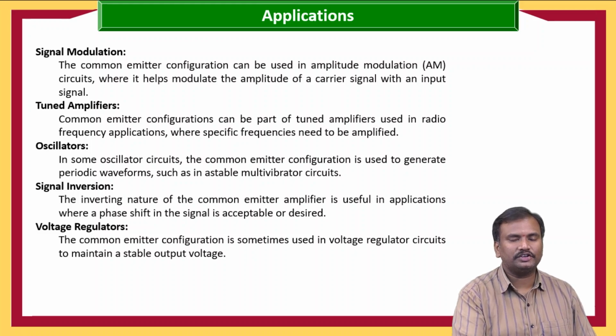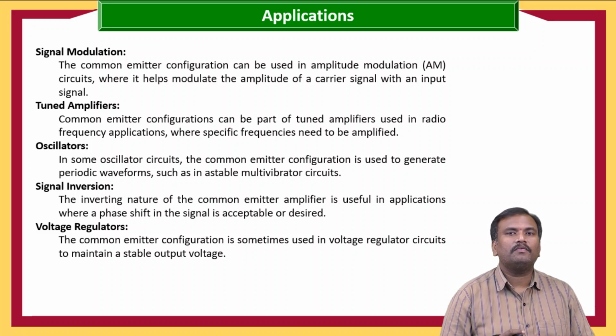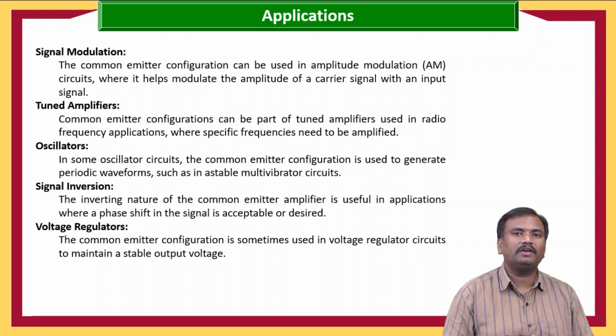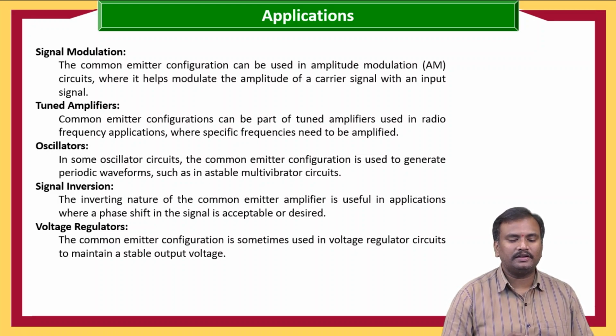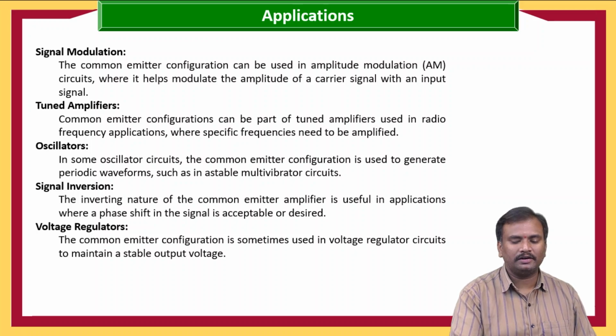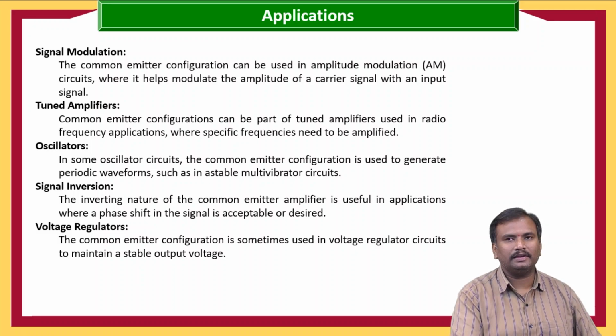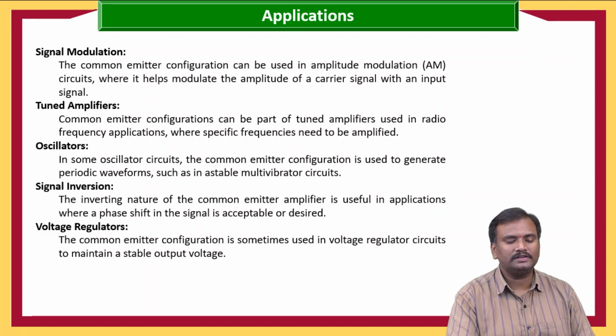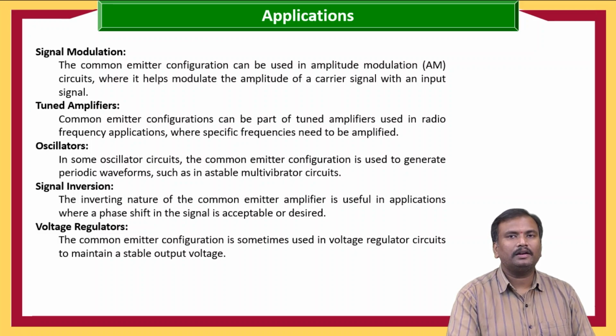And signal inversion: the voltage we give becomes 180 degrees out of phase, so signal inversion happens naturally. In applications where the phase shift of the signal is acceptable, we use this common emitter amplifier.